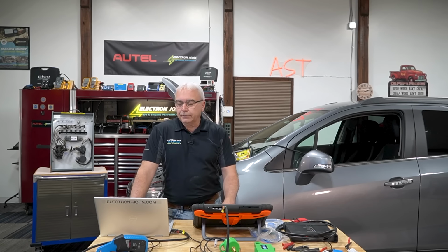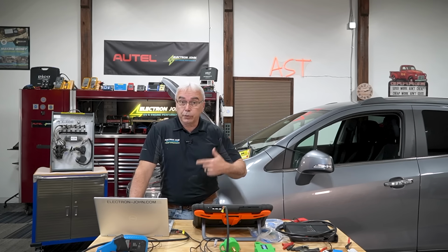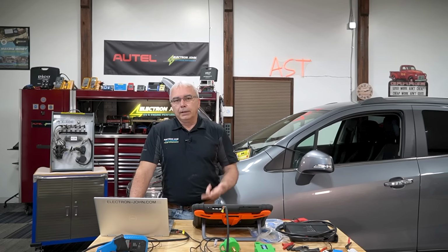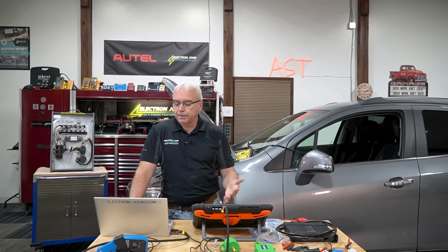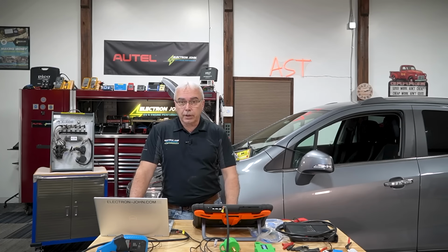Those 6 lines of data that I'm concentrating on are the temperature inputs, the O2 sensors, both pre and post CAT, my load sensor, whether MAP, mass airflow, whatever, my demand sensor, which is throttle position, and my RPM sensors and fuel trims, both short-term and long-term.